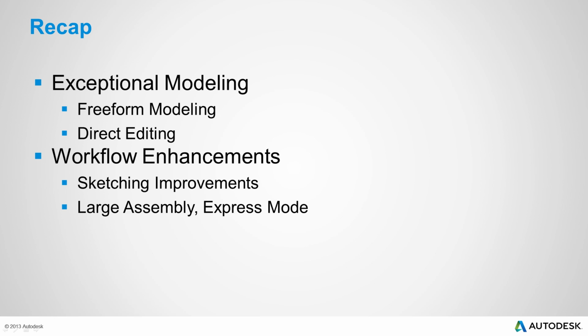Then we took a look at the direct editing tools, which allow Inventor users to work with geometry from either native Inventor geometry or non-native geometry from other CAD tools. These are the tools where you essentially can just grab model geometry itself and then move it, delete it, rotate it, scale it.